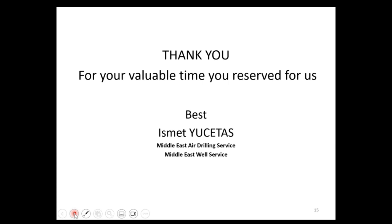For long-term application, if you use the coil tubing pipe or a parasite string and pump a high volume of almost pure carbon dioxide, you should be careful. It could become brittle. When you pull it out, you should be careful not to break it.